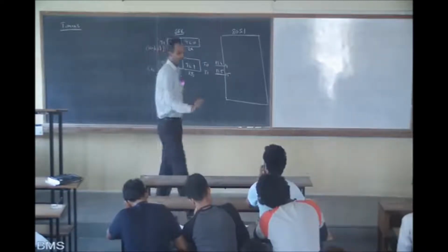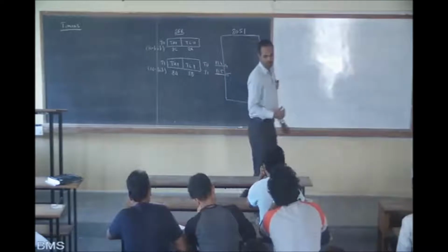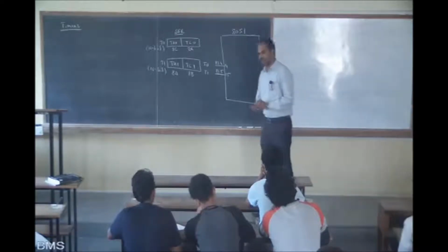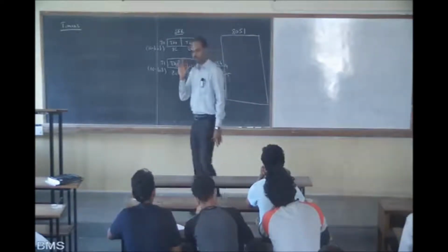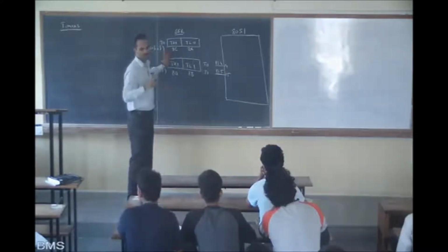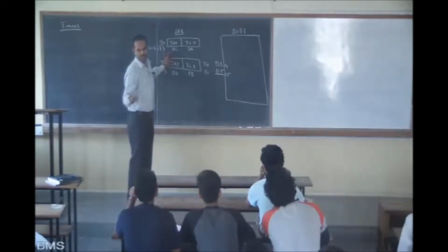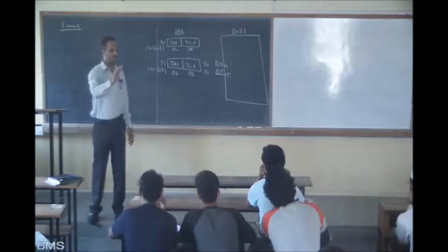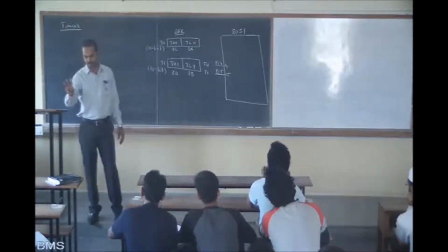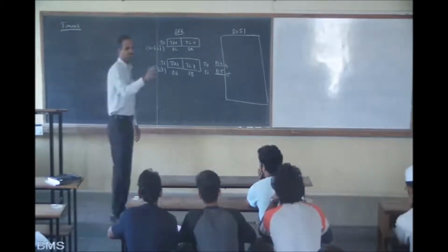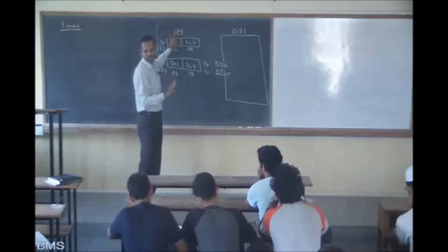What is the maximum and minimum value we can expect when it is 8-bit? It starts from 00 and goes up to a maximum of FF. When it is 16-bit, the maximum is FFFF. Beyond that, what happens? After all FF, it comes back to 0, 0, 0. This is exactly the same in a binary counter. We discussed a 3-bit counter in DEC: it starts from three zeros, goes up to three ones, and after that it comes back to 0 again. Same phenomenon here.